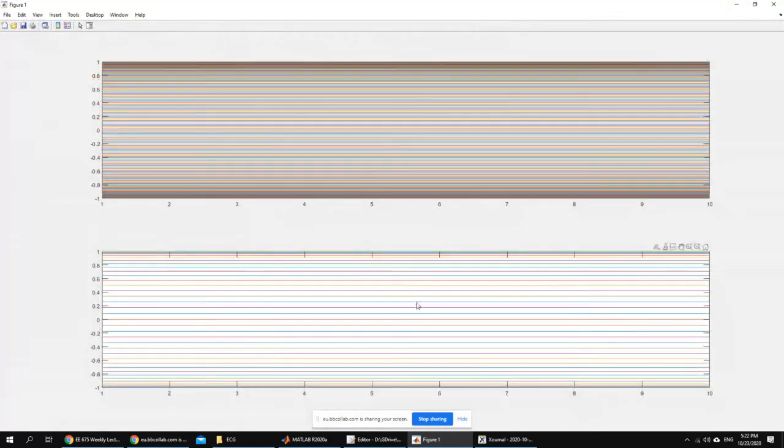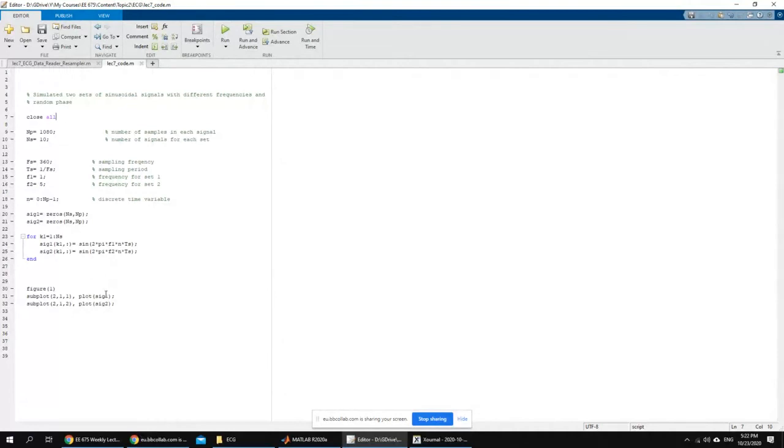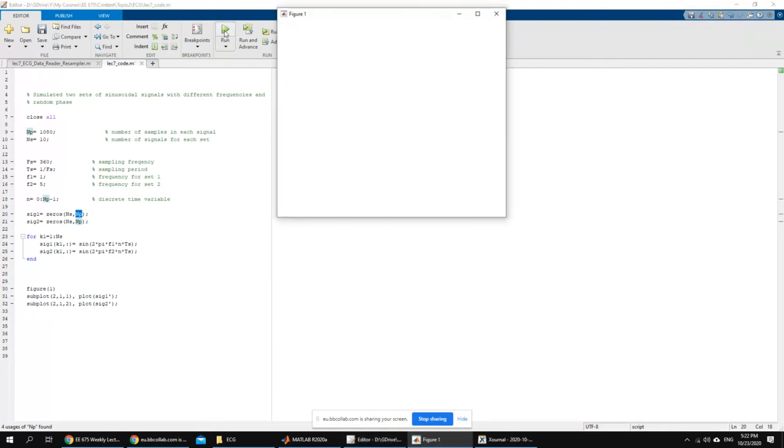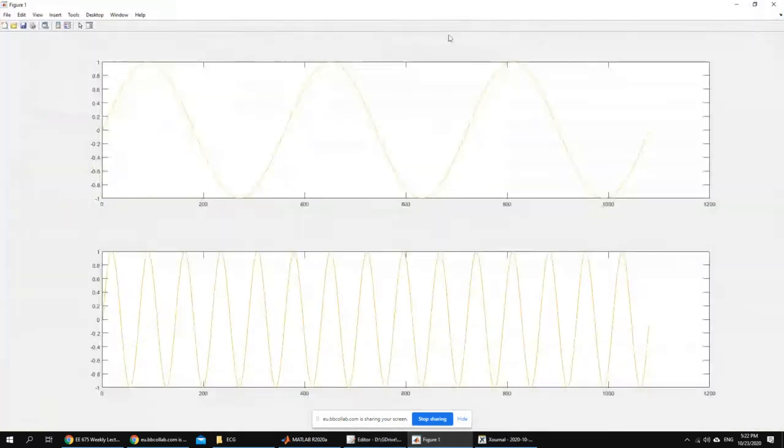It actually looks very strange, right? So basically, what you're supposed to do in order for MATLAB to do that properly is just transpose that. Transposing means that instead of the array being ns by np, it's going to be np by ns. So I'm moving the samples to the first dimension of the array. Let's see what's going to come out of this. Actually, they were all drawn here,